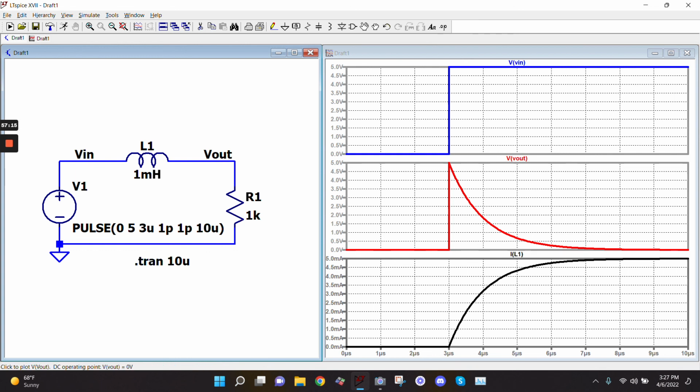It should just stay at 0 because if Vn goes to 5, the voltage across the inductor doesn't matter to us. A voltage across the resistor matters because we don't want to change the current. So V out should stay at 0, right? So let's run this. And it stays at 0 when this pulses, and then the current and the voltage basically go up together because V out's going from 0 to 5, so my current goes up proportionally, right? That's basically Ohm's law right there. V is equal to I times R. If I took this I and multiplied it by 1K, I get this waveform for the voltage, right? And that is the inverse of a capacitor. If you had a capacitor with a resistor in the front, then it looks like that. Yeah, exactly.